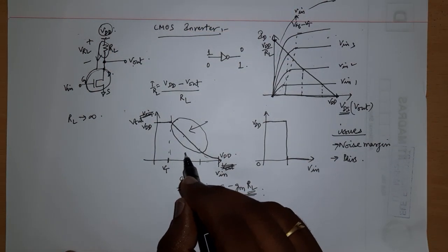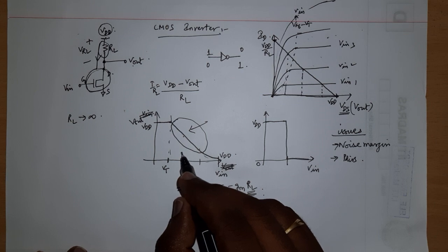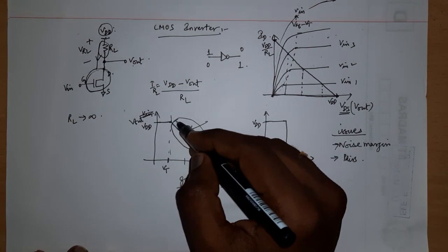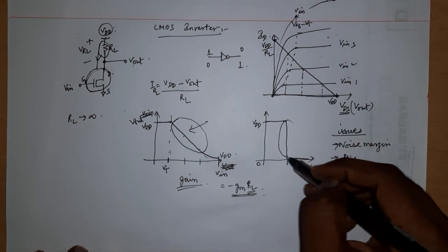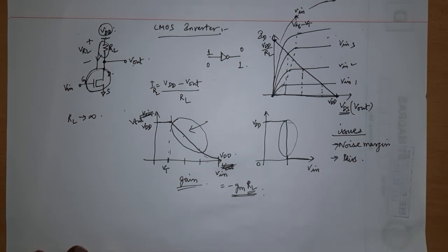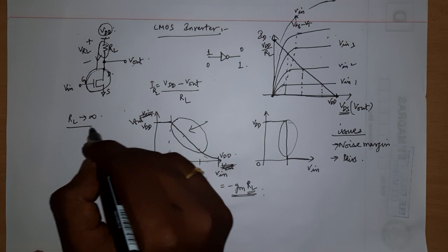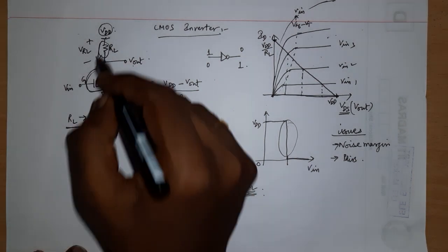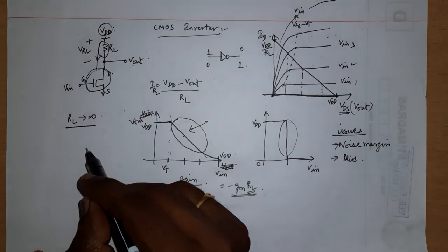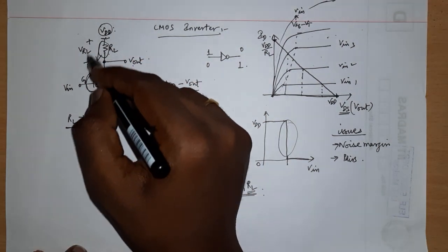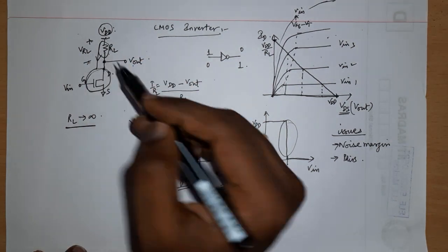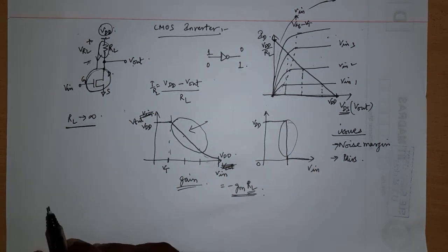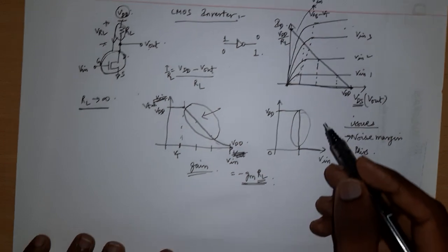So if nothing comes out at the output voltage, then this transistor will not remain in saturation. Okay, and only when it remains in saturation will you get a very large slope like this. That is when the gain will be maximum. So I am actually greedy to want a larger resistance at the load, but I cannot have it, because if I have it, then I will have a large voltage drop that will make my transistor come out of saturation and I will not have this slope.